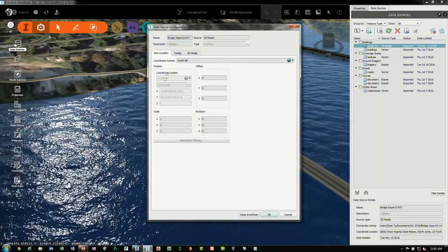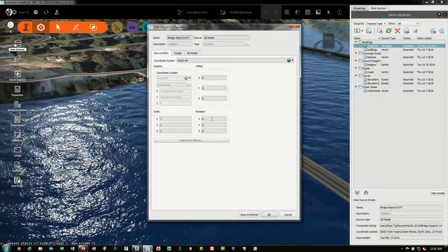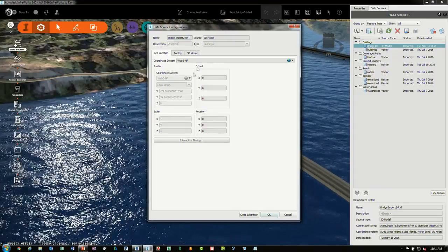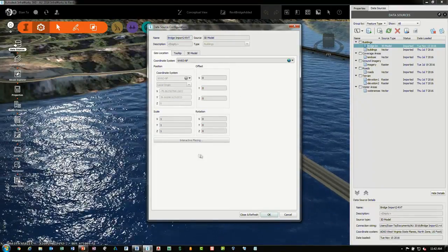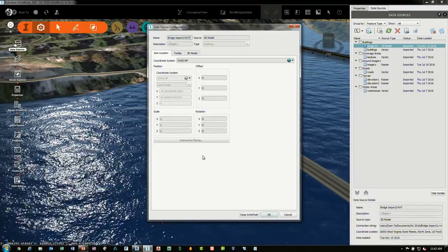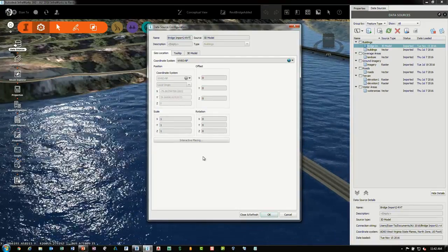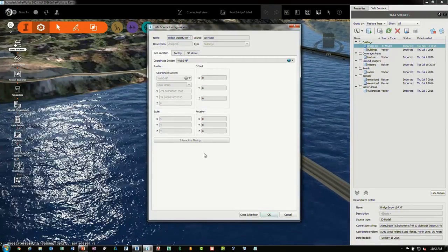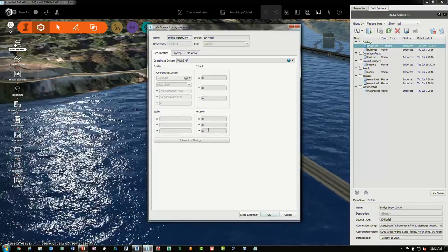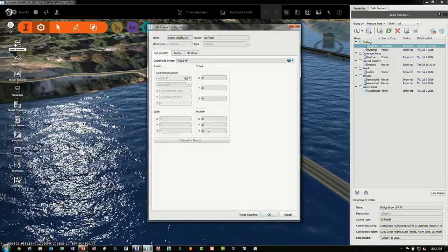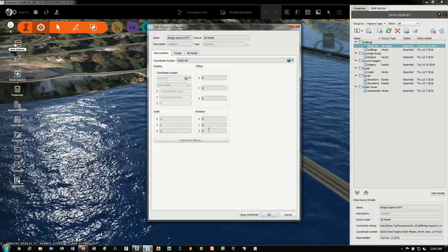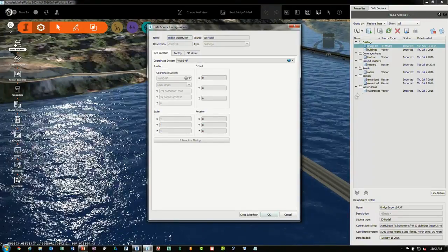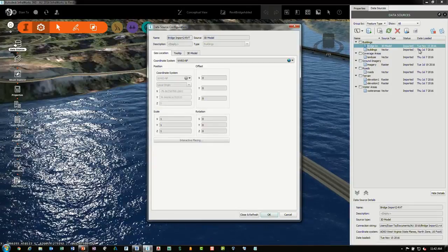So by default, when you bring the Revit file into InfraWorks, this information will not be assigned properly. And you'll have to make the necessary adjustments. And then it'll say imported. And like I said, if you pull the handout and go through the step-by-steps, because in the handout I have it actually written out step-by-step what to do, even down to the point of the coordinate system, then you'll understand why does it say imported versus configured. Okay.